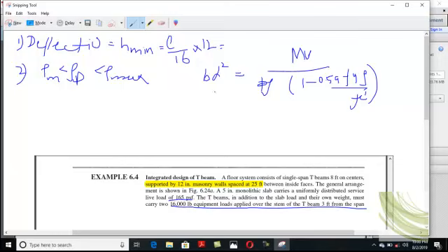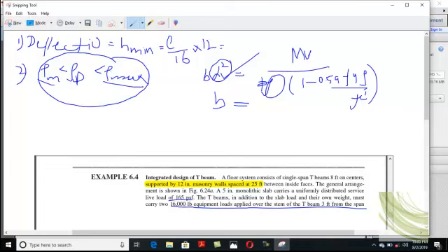So from there you fix your width, and this rho is basically fixed. This rho is basically selected in between rho max and rho minimum. So it will give you the minimum and maximum value of your depth. Okay. So the depth which is selected from this criteria will pass this check. Clear? And you have no tension about this check as well as your depth. So it gives you minimum depth and maximum depth. For rho max and rho minimum, you will determine two values of depth. You select the depth value in between these two values, so your minimum depth criteria will be fulfilled.